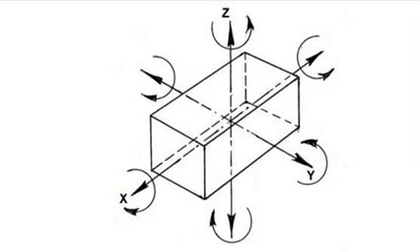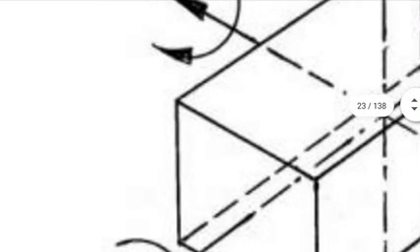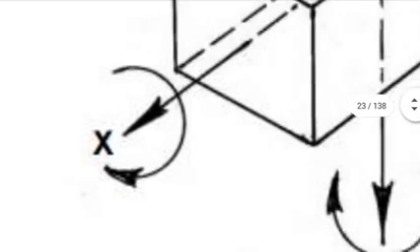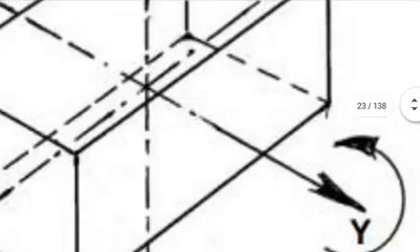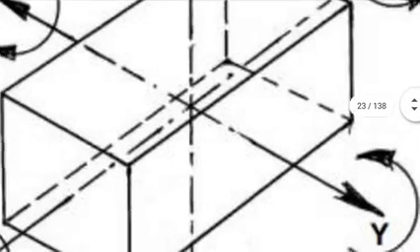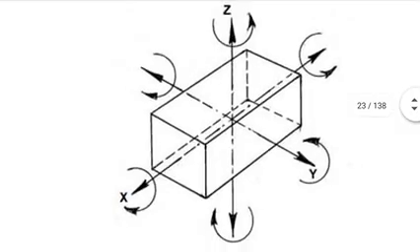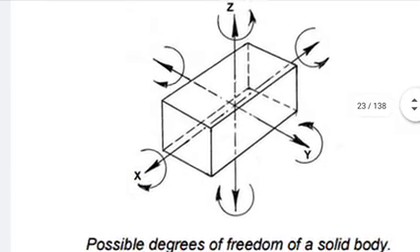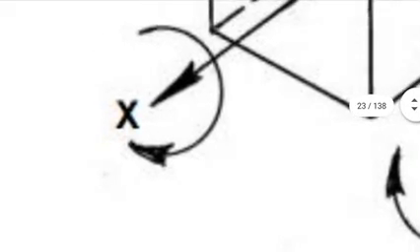There is a possibility that if a hole is to be made on one of the edges of the component, you can see edge 1 or edge 2, or the component may be at edge 3. There may be some drilling or sharp operation on the edges. Due to the tooling pressure, the component may wobble in the x clockwise and x anti-clockwise direction.